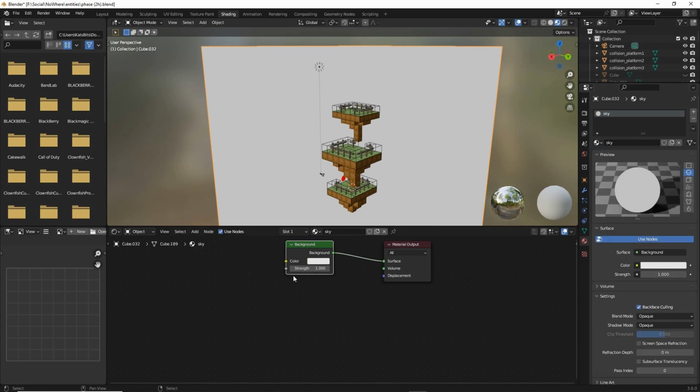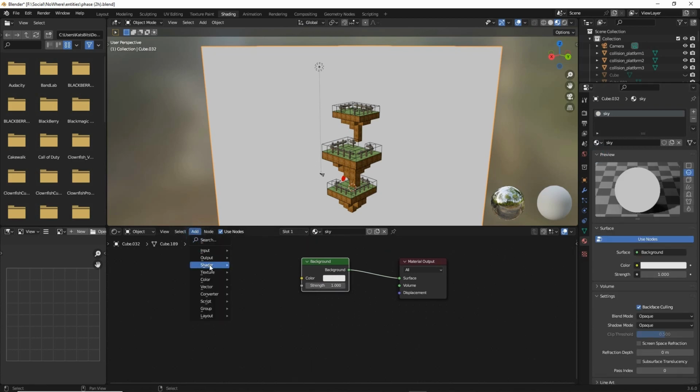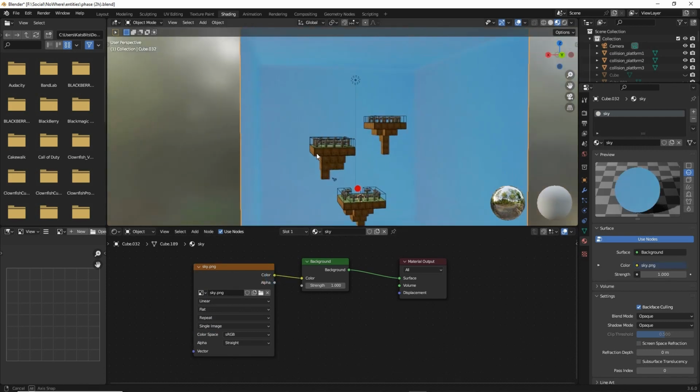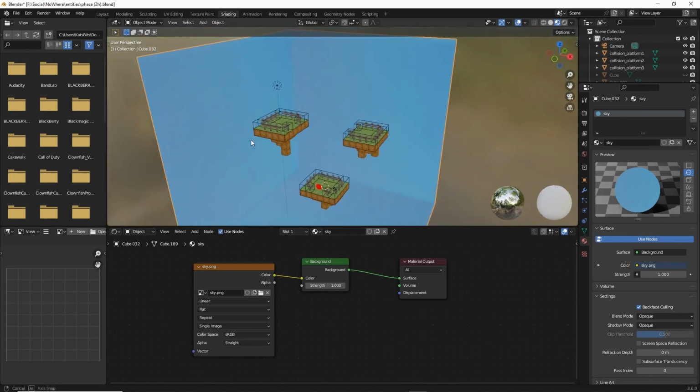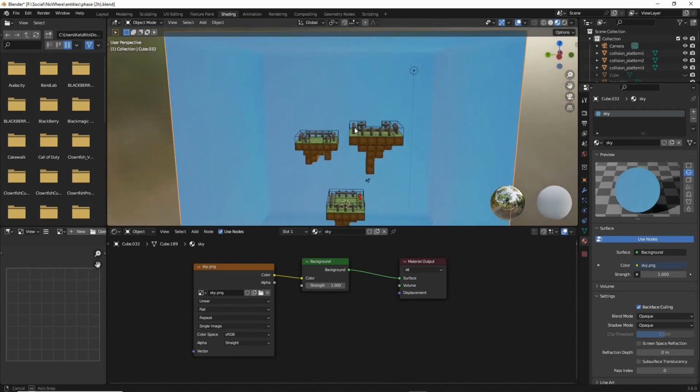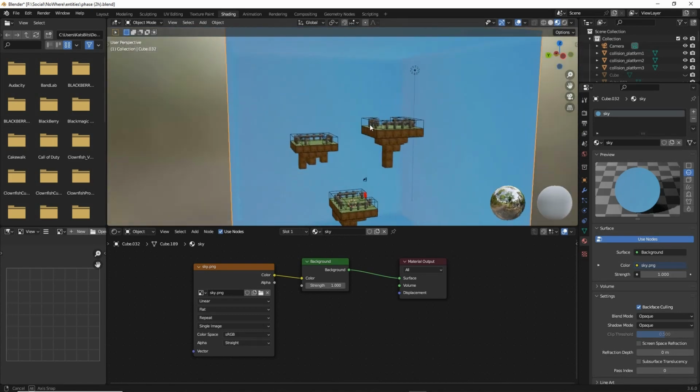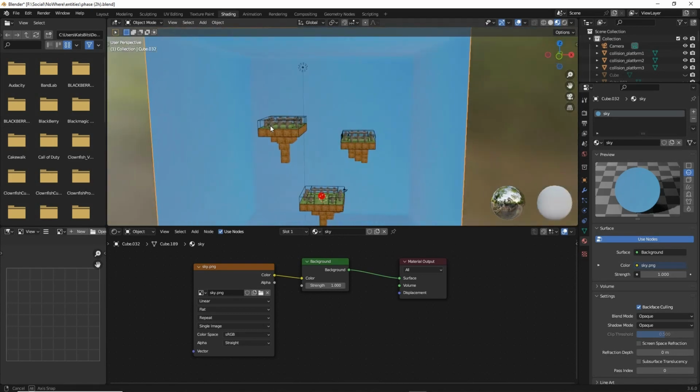Let's just preview that. So what we want to do here is add texture, image texture, and as we loaded in our sky previously, we can use the browse image to be linked. Select from the list and then link color to color, and that's our image. And we can see that that's basically got rid of the shading that was present before.